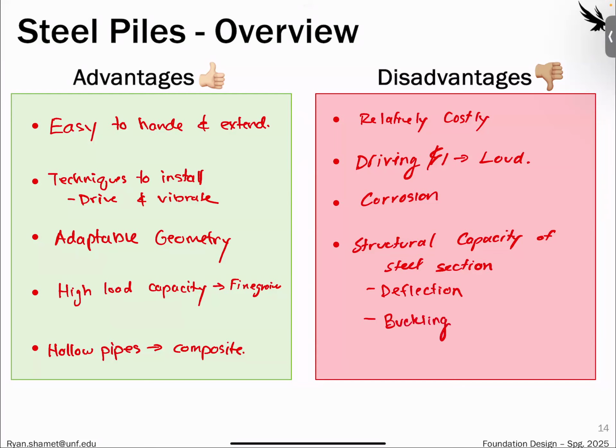So this is the area where a lot of times geotech and structurals are lumped together. Yes, we designed the capacity for this, but we also have to account for the physical loading on the pile and not exceeding any of the capacities of the structure itself, let alone the soil structure interaction around it.